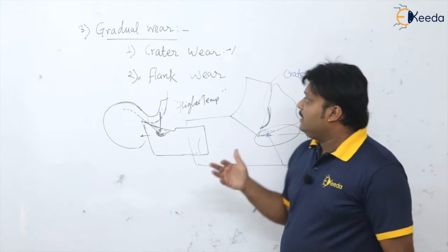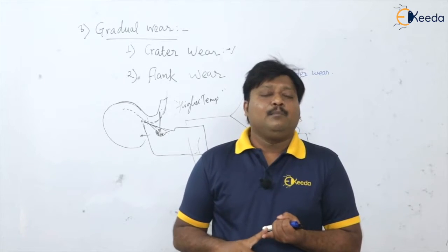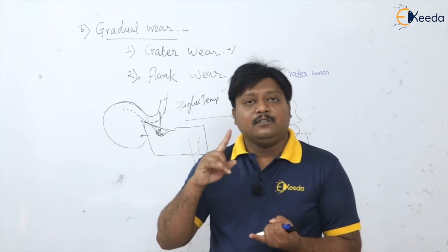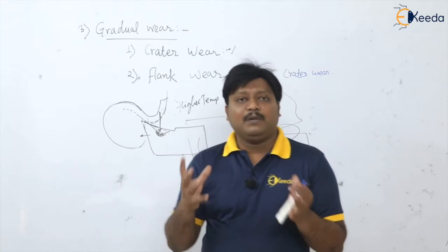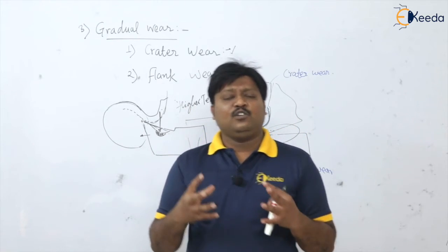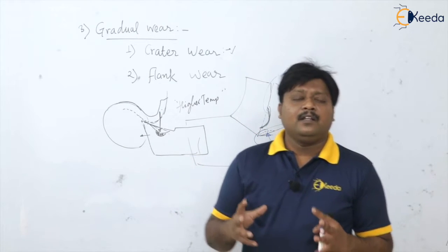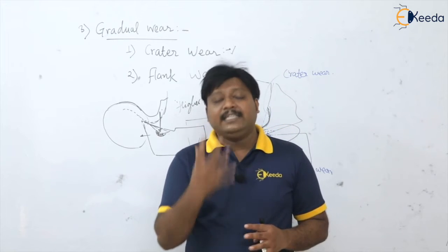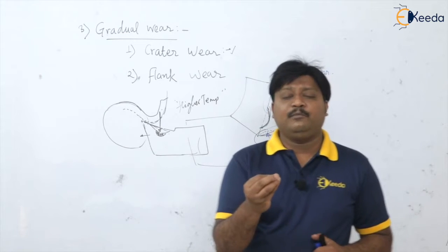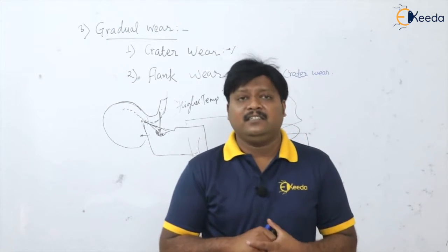So actually in flank wear, of course, there is the abrasion between the chip and the tool, that is the action of abrasive particles, microchips. Then again there is the action of the fragments of the built-up edges, which are also present there. And the third thing, very predominant: as in crater wear diffusion is predominant, in flank wear the adhesion is predominant.